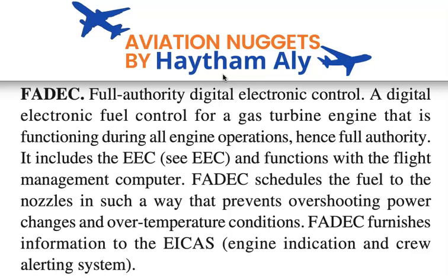So what is meant by FADEC, everybody? Full Authority Digital Electronic Control or Engine Control. The FADEC is a new engine control system, or a digital engine control system. Nowadays, engines are electrically controlled, like we speak about the flight control system, fly-by-wire. So in this case, engine control is also by wire.